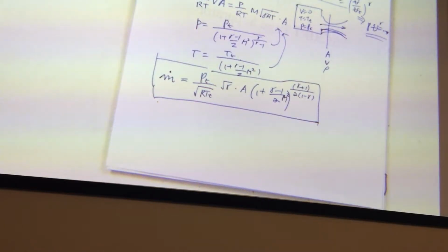In a supersonic wind tunnel, you may have an open circuit, you may have a supersonic closed loop wind tunnel. But what happens is that you have this converging-diverging nozzle, and you get to supersonic flow, and then you have a constant area test section. That's what it is. So in a sense, you can drive your supersonic wind tunnel using a rocket if you want.